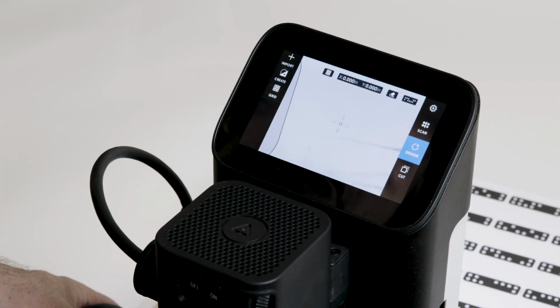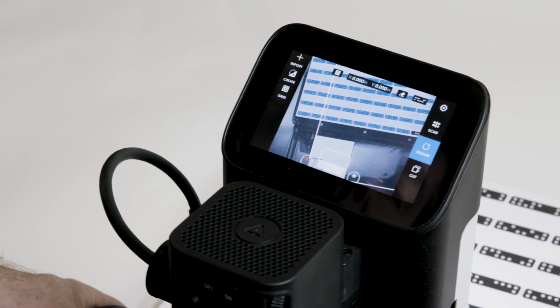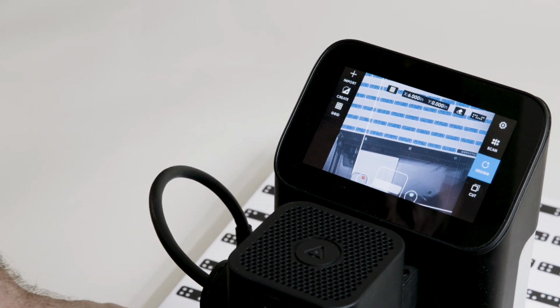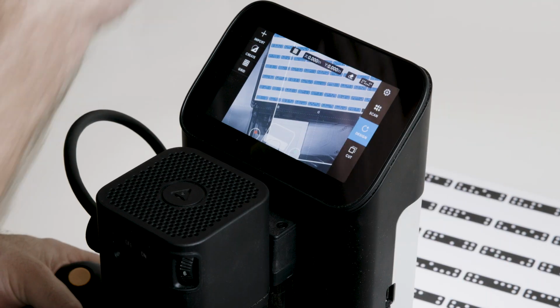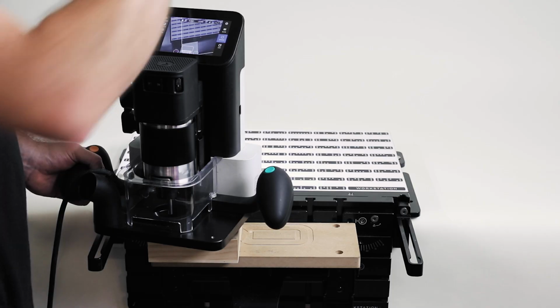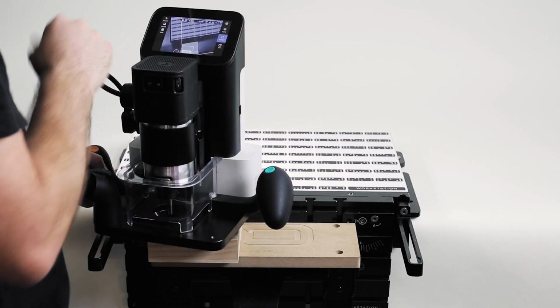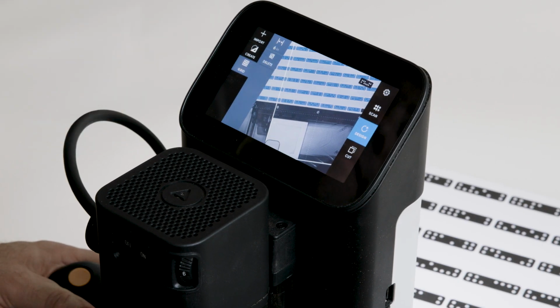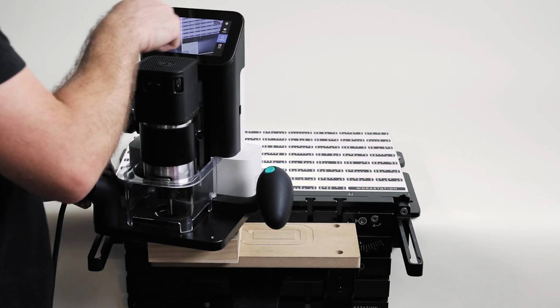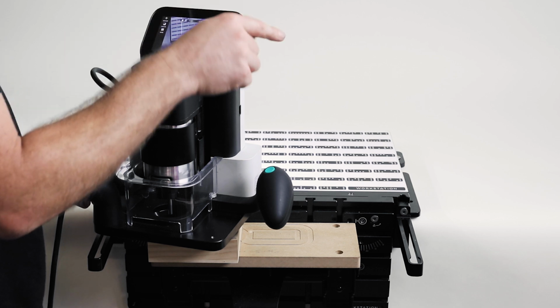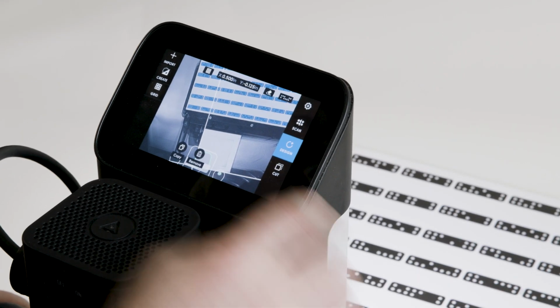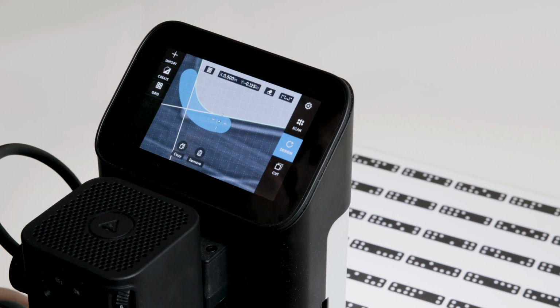And now you'll see, if we zoom out, our grid spacing is bigger than this object itself. But that would enable you to very quickly confirm you're aligned to 0, 0 on a large object. And then the opposite is also true. Grid, modify. Once again, we don't have to reprobe or anything. We're just reusing that initial probing information and going in and changing the increment here. So I'm modifying this down to 0.18, and we'll zoom in again.